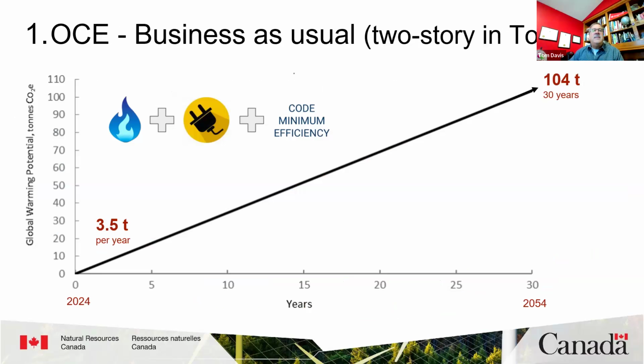So let's take a look at some examples of operational carbon emissions based on a two-story house in Toronto. This type of model will be different depending on location, as the greenhouse gas intensity of the electrical grid varies by location. The assumptions for fuel-related emissions are built into HOT 2000 and MCE squared.